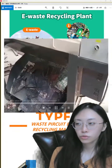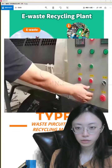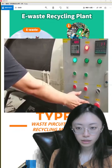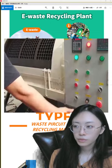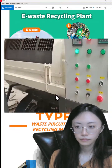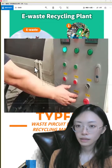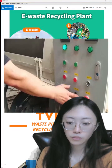It's important to control the temperature of the board, of this heating zone. If the temperature is very low, then the components will not just remove from this board, but a very high will have damage of this bare board. Almost 200 degree. Then just by using the heating and vibration, then the components will just remove out.